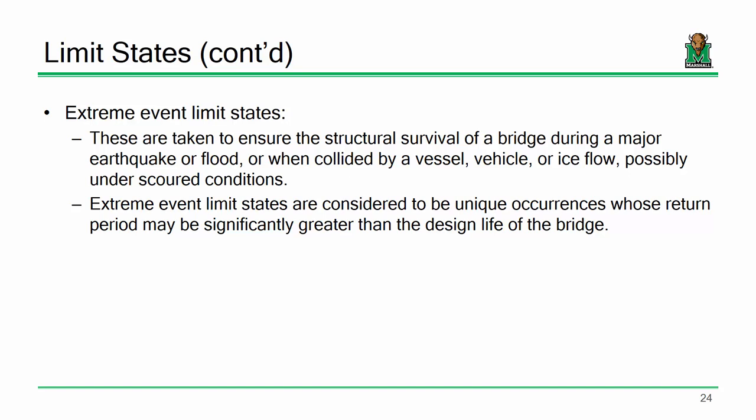Where the extreme event comes into play is this. The way we handle earthquake engineering and earthquake design is so fundamentally different to the way that we handle day-to-day operation design. This building is subjected to another very significant lateral load, okay? In the world of structural engineering, we have two main lateral loads. One of them is earthquakes. What's the other? Wind, okay? Now, wind wouldn't be an extreme event, would it? No, wind happens all the time, right? I'm sure there's some breeze right now, okay?